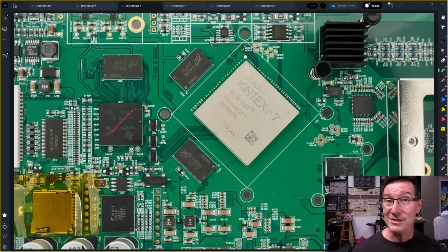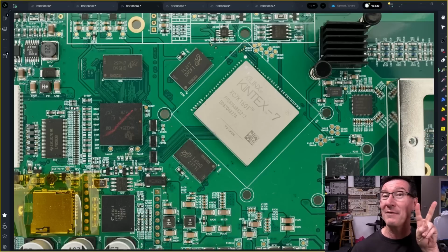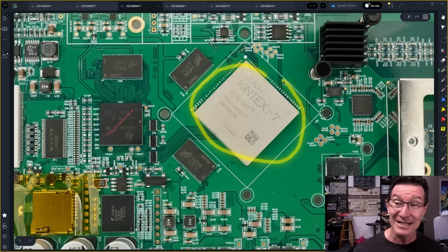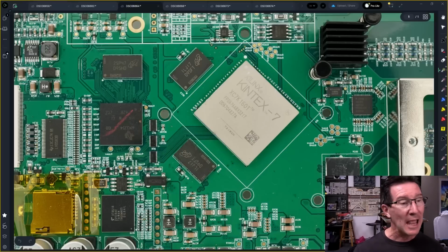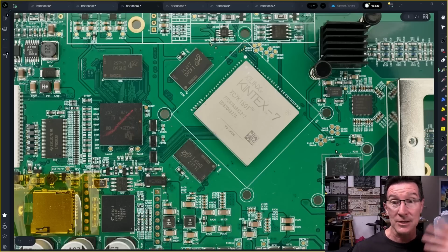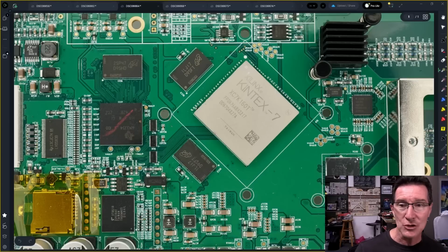Now, if you know anything about semiconductors and pricing, you'll know that the two costliest parts in this thing are going to be your gigantic big FPGA here. It's a Xilinx Kintex 7, that's one of their big daddies, and also the 2.5 gig sample per second DACs in this thing, because these are what, 14, 16-bit jobbies, right?